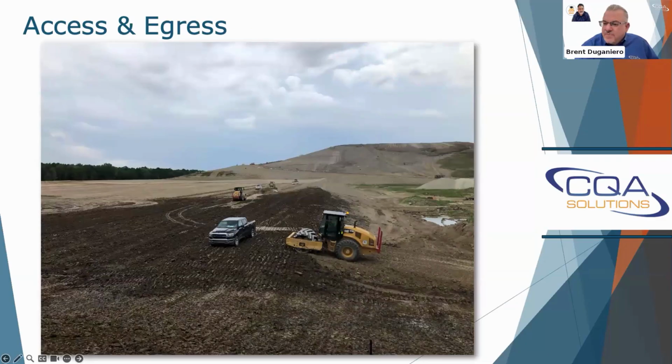Although we're not doing geosynthetics yet, we were building the berm, and that pickup truck is the fellow that was doing the density testing. So had he been outside of that truck, maybe near the top of that berm, that ramp there, squatting down, prepared to take a test, maybe that compactor was coming up slope, and because of the angle, didn't see him. So as they're coming up the slope, they might not be able to see something that's at the top. So maybe we need a flagger.